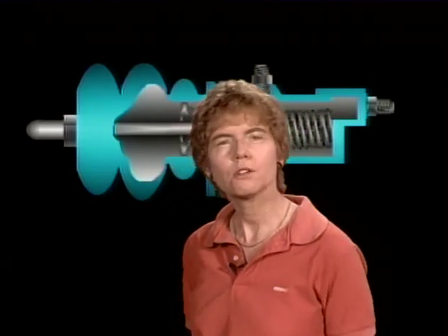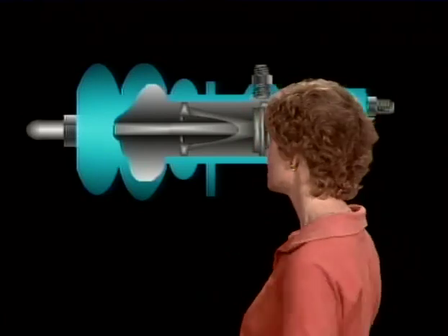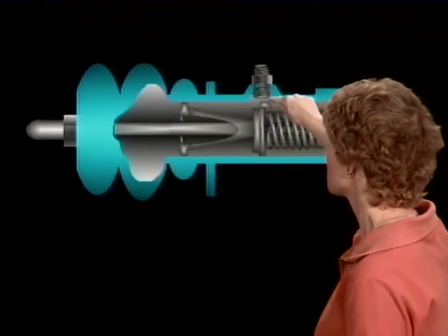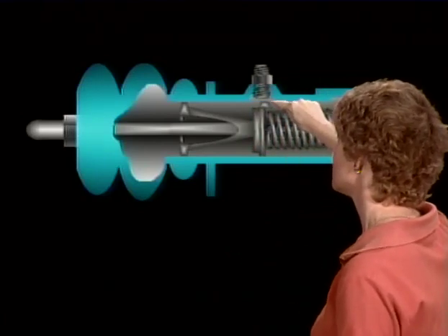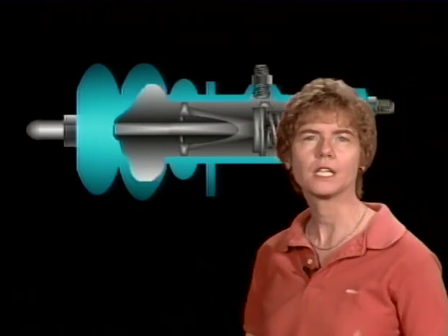Now, let's assume that a pilot reports to you that the left brake on an airplane is dragging. The left brake is dragging excessively. One cause, the most probable cause under the conditions the FAA will give you, is foreign particles stuck in the master cylinder compensating port. Because if there's foreign particles in here, if that port is restricted, the brakes will not release properly and the brake is going to drag.